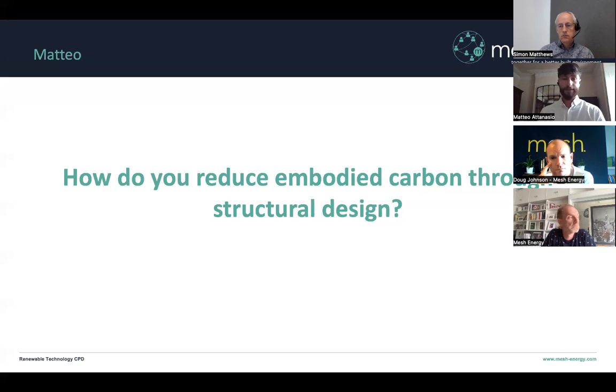So that's fantastic. Then there's build clever. So using appropriate structural configurations, trying to avoid big transfer structures, trying to have regular grids and standardizing grids across different use classes. So buildings can be adjusted and changed. And what was once a factory can now become an office, and what was once an office can now become domestic space. And that's the way that we build in reuse of a space as we're designing.